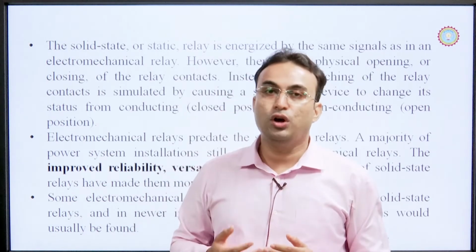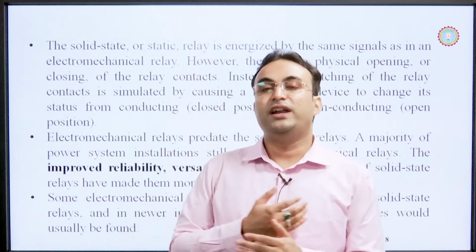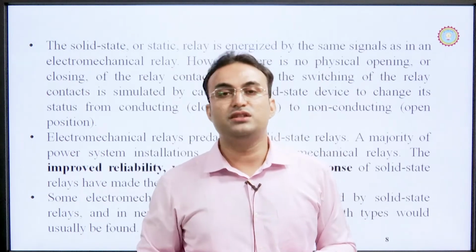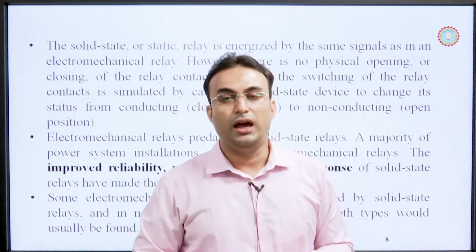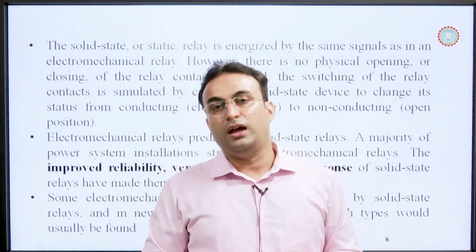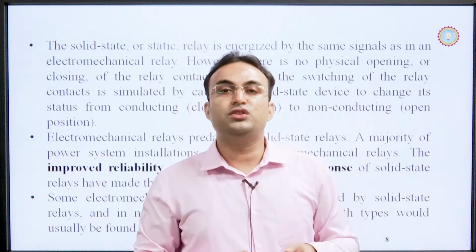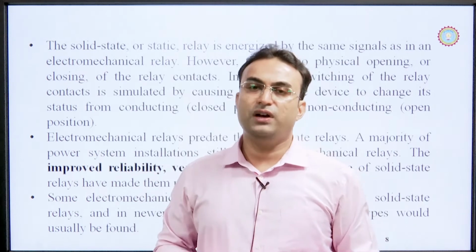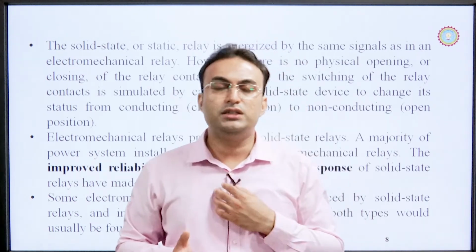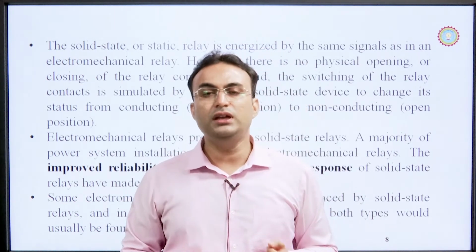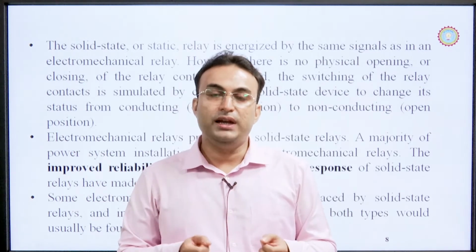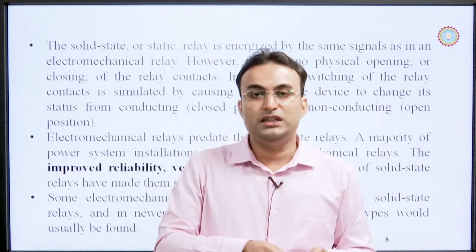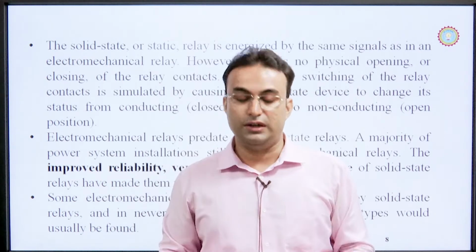step by step, because solid state has some advantages: there is no moving part, there is no wear and tear in the solid state relays, there is no noise, and the overall size of the solid state relay is very compact. That is why we are going to replace the electromechanical relays with solid state relays. So, electromechanical relays are replaced by the solid state relays.